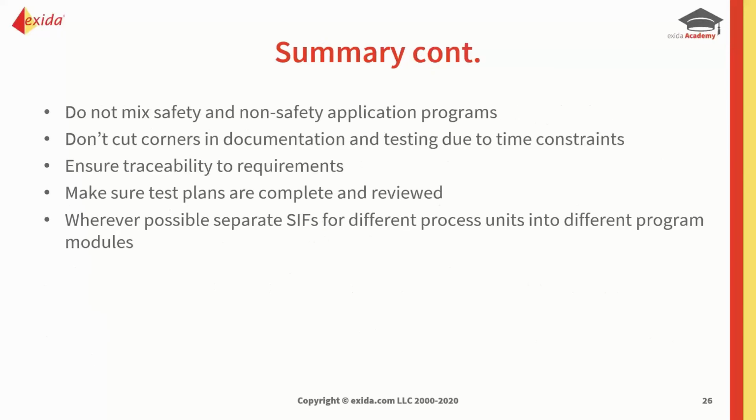Do not mix safety and non-safety application programs. I can't remember the number of times I've been saying this in my classes to people, that you must make sure you don't have safety and non-safety together, because if you do, everything has to be treated as safety. So if you're just putting it into the SIS for convenience, then think again.